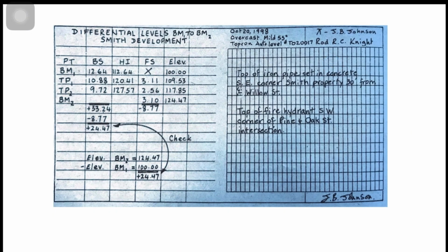So class, in surveying, what you measure in the field is temporary, but what you write down and mark is what will last forever. That's why we will talk about the importance of field notes and the field marking of a benchmark. Field notes are the permanent record of all your observations. The numbers you write down become the basis of your computations, maps, and designs. Why are they important? Field notes prevent mistakes. If you make a misreading, it can be checked because it's clearly recorded.